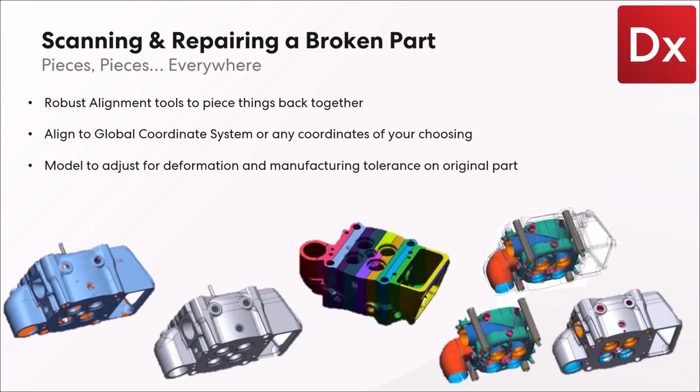Once we did that, we did a bulk model of the exterior of the part, getting what we can for the base reference geometry on some of these holes and locations. We then took the interior volumes that we scanned, since it was sectioned, and used those to create objects to Boolean out of the rest of the block.